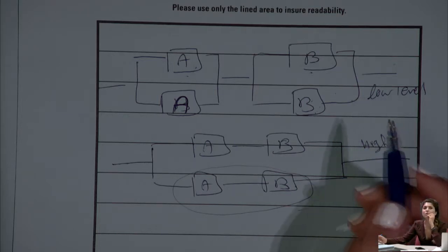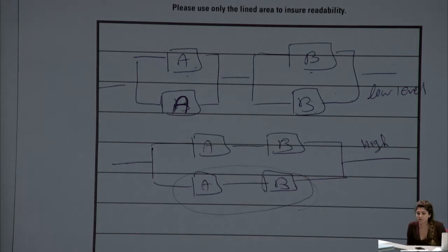Depending on what the critical components or critical functions in your system are, you can define whether you want a high level of redundancy. Do you want the whole system to be redundant for that specific subassembly or function? Or do you want to go based on some of the components that are critical in that function to just consider component level redundancy? Sometimes you might have both. So within a system that has redundancy, you might have component level redundancy as well.